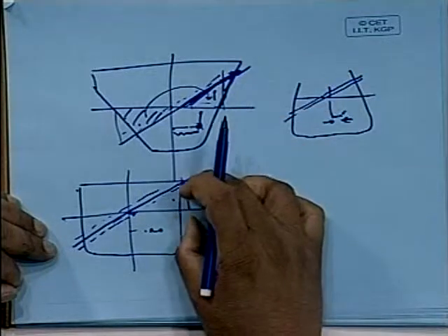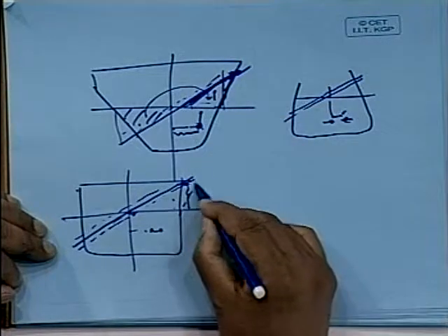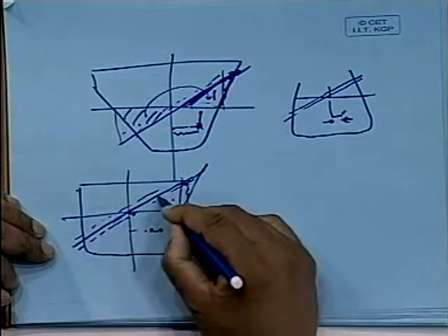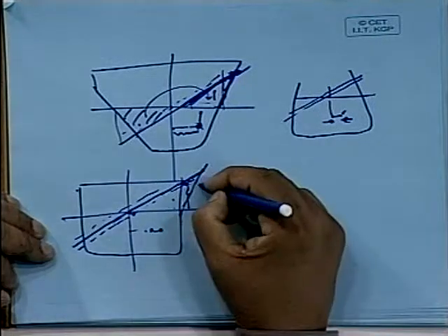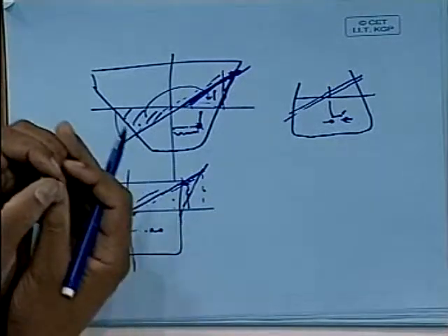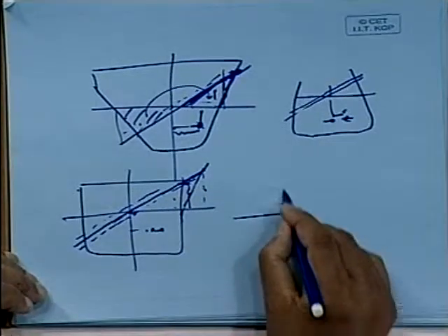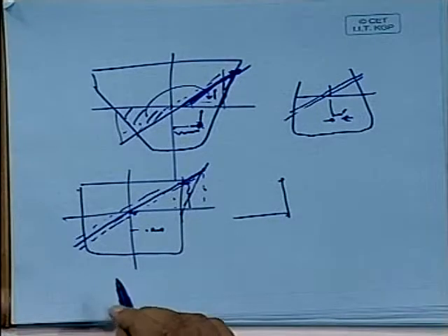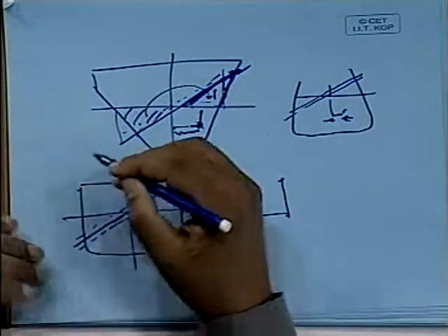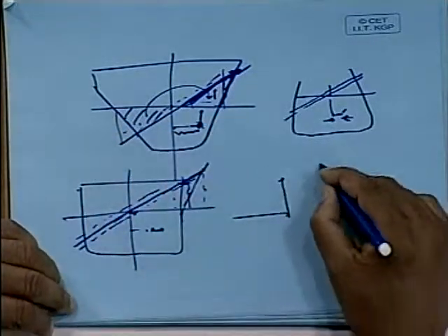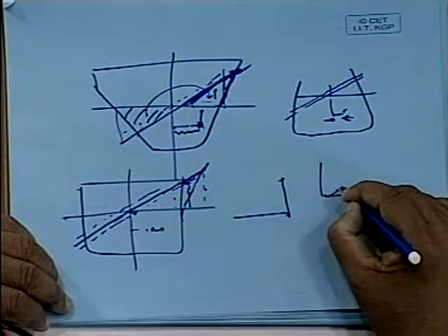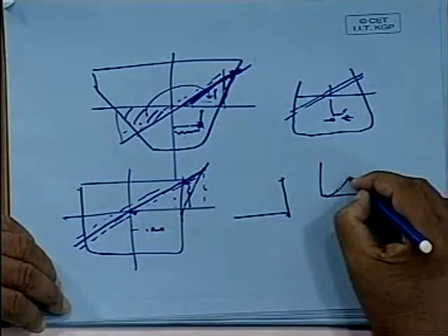This height is typically a little more than that, because here the shape was like that, so the shape is higher. If the hull was like this, then this would have actually gone to a higher point. So the center of gravity vertically would have been higher. Effectively, that means you have shifted the weight further this side, further up, and the rate of GZ increase will become larger. So initially GZ is increasing at a certain rate, but as the angle goes up, it goes up at a higher rate.